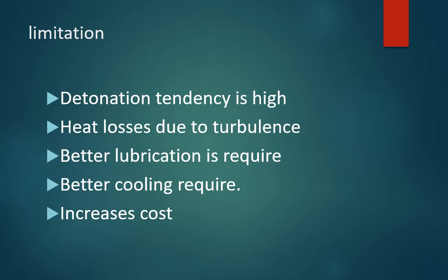Supercharging involves the introduction of more components, and the cost and complexity of the engine would increase, right? These are essentially requirements that come about with supercharging. That is, we need to ensure that the mechanical loads and the structures can withstand it, and we have to introduce more components that will increase the cost and complexity of the engine. So detonation tendency is also high, right? We are increasing the pressure. As the pressure increases, the detonation tendency is also increased.